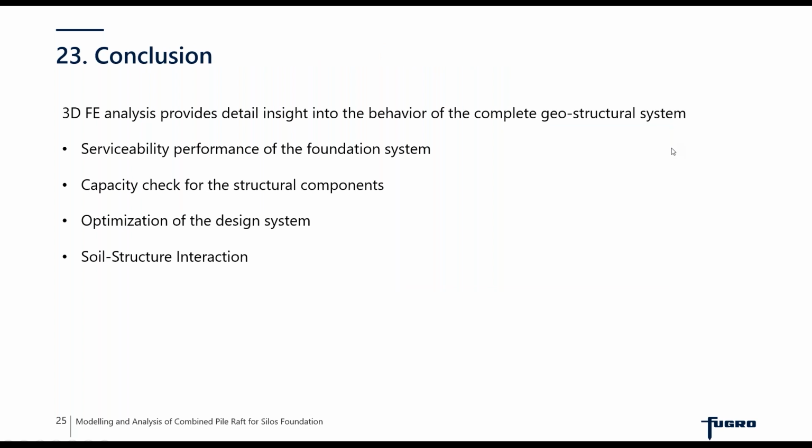So I've shown you the various outputs. The 3D finite element analysis provides you a better insight into the behavior of the complete geostructural system. You get the serviceability performance of the systems, you get to check the absolute settlement and the differential settlement across the foundation, and you check the capacity for the stresses generated in all of your elements, whether it's raft or piles. And of course, if you are in the preliminary stage of the design, you can always optimize the design system.